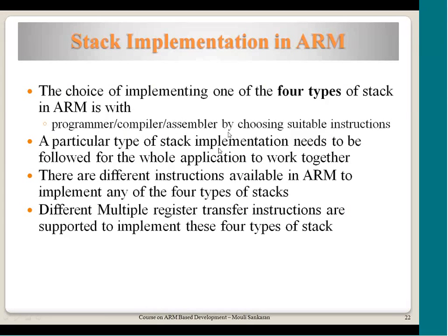But the thing is, once we decide on a particular implementation for the whole application, it should be the same. We cannot use one instruction which assumes empty and descending, and then while taking the data out, use an instruction which is meant for ascending and full. Then what you push, you may not be getting back from the start. So the flexibility is there, but needs to be taken with a pinch of salt, and we need to make sure, especially if you are writing assembly code, that you use proper code for both pushing and popping values into the stack and taking the data from there.